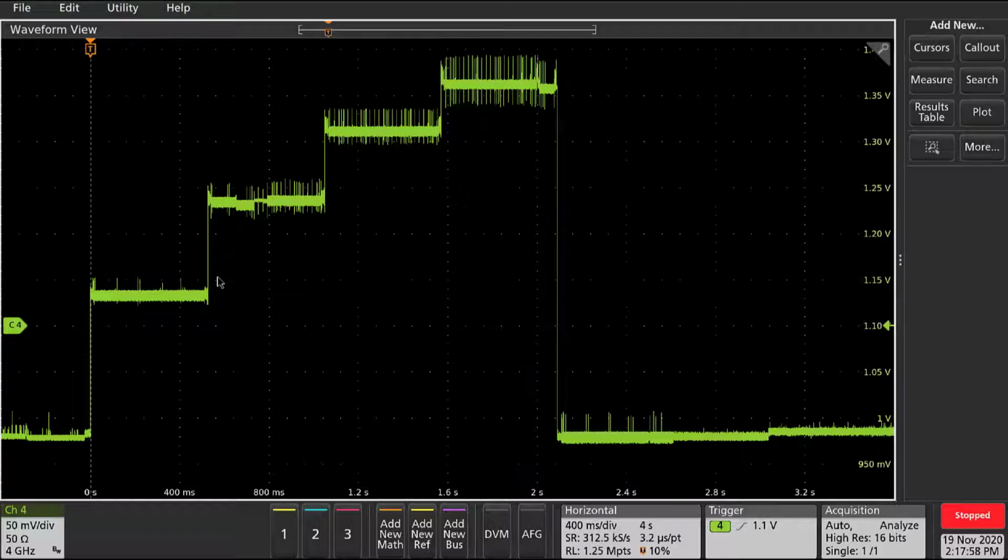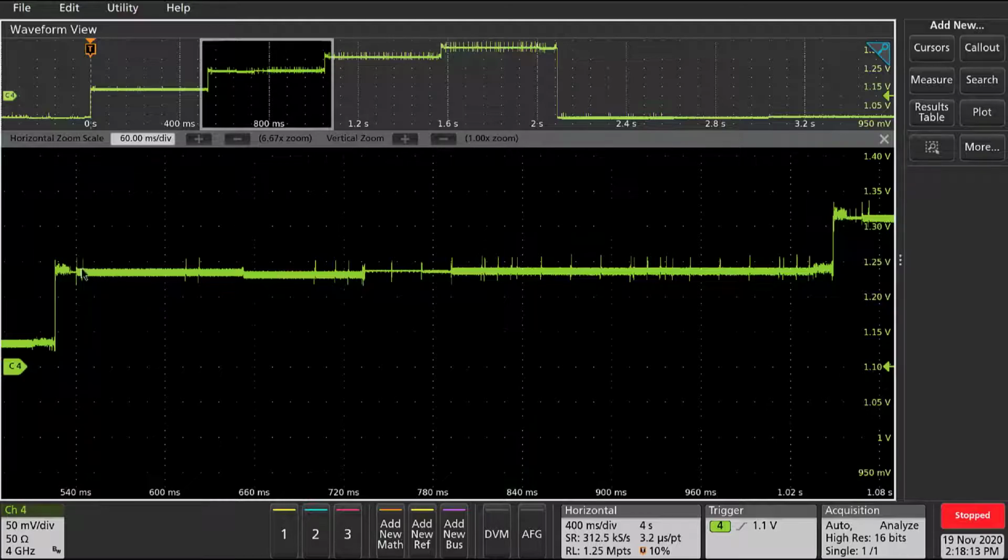Now the DC transitions that we can see are a lot more complex than that. For example, if we zoom in on just this pattern here, what we'll notice is that the DC offset there is actually much more complex. So you can see there's transitions on transitions here. There's even different ripple and different noise values that are being coupled in each pattern. So there's a lot more complexity on this particular rail that was basically unnoticed once we coupled everything back down to zero, or to DC, or to ground in this case.